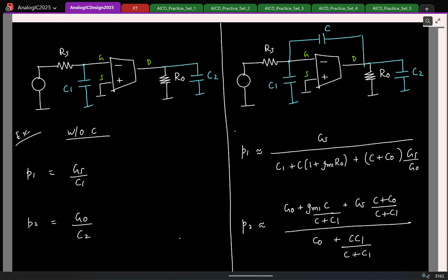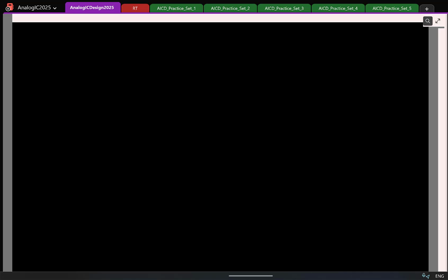Let's quickly try to see why the pole locations here make sense. Let's start with the low frequency pole. And for that I want to take a small digression. So let us say you have a voltage amplifier with a gain of -8. If I mark it like this, what kind of a control source am I talking about? Voltage control.